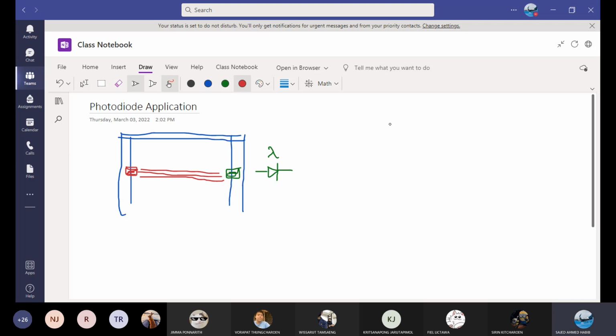So the photodiode will conduct like this. If I draw the curve, let's say for a regular amount, the photodiode is conducting. Let me put a blue line. Maybe this is the current. This is the reverse current that is being detected by a circuit. Now someone is passing, what will happen? The beam gets broken. When the beam gets broken, what is going to happen?